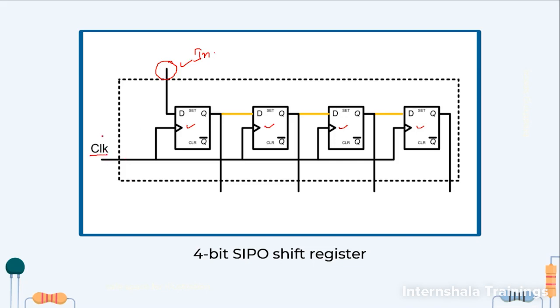Whenever we have the rising edge of this clock, this input will be loaded, but this one will be loaded only when we shift the output from here to here. So we will be transferring the data in this, and because this flip-flop is getting the same clock signal, it will happen on its own. We don't have to trigger any extra signal.